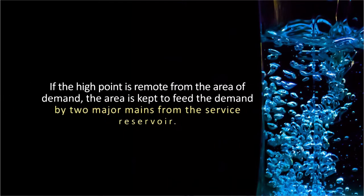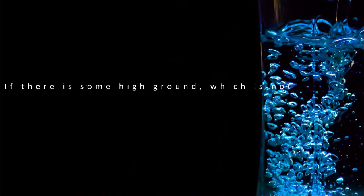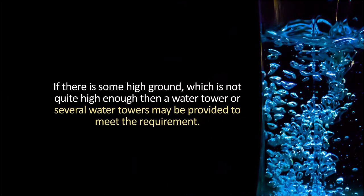If the high point is remote from the area of demand, the area is kept to feed the demand by pumping from the service reservoir. If there is some high ground which is not quite high enough, then a water tower or several water towers may be provided to meet the requirement.